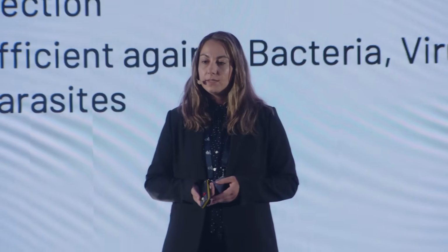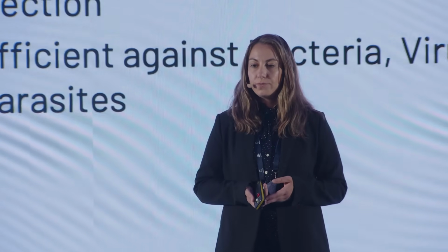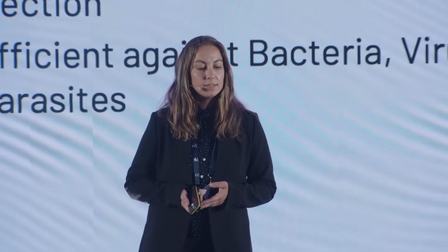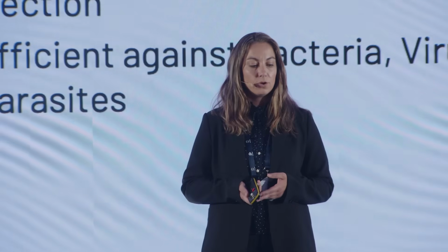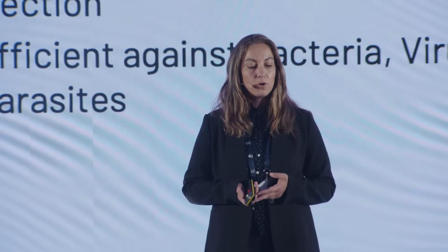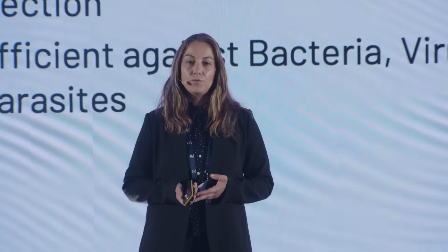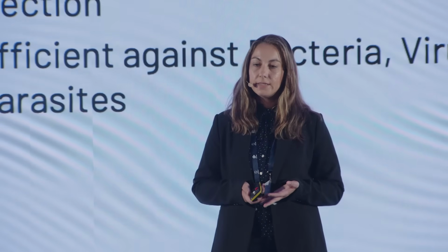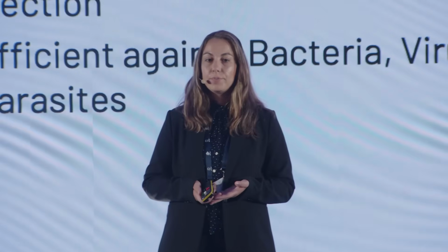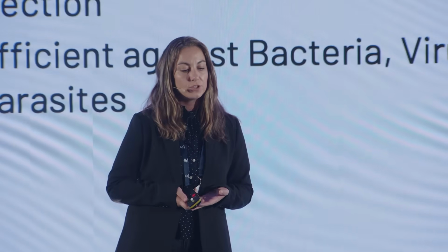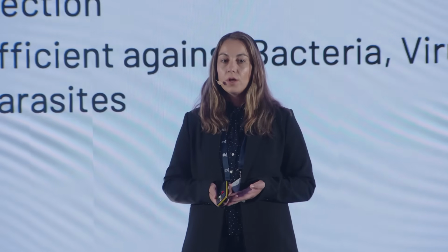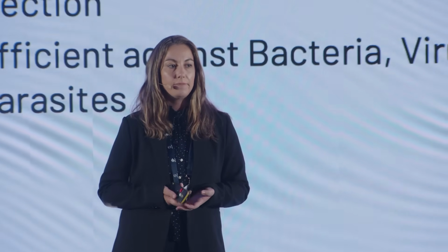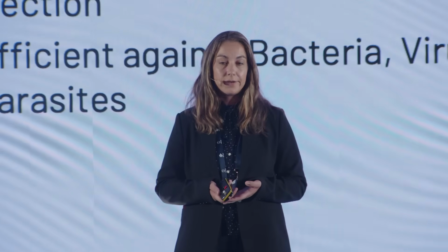Ozone is a good candidate in aquaculture to improve the overall water quality. It's a very strong oxidizing agent, reacting rapidly with non-biodegradable and degradable organic matter. In presence of ozone, the protein degradation is enhanced, and the water clarity, UV transparency, and the processes of filtration, nitrification, and coagulation are improved. Ozone is also a very good disinfectant, able to kill virus, parasites, and bacteria.